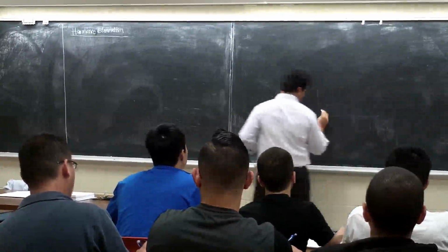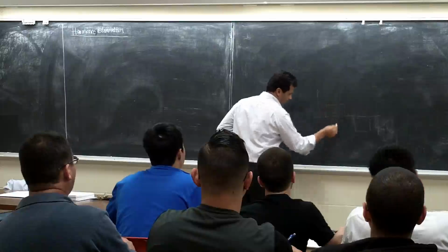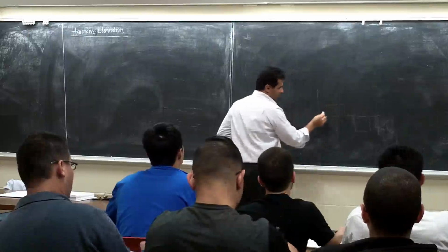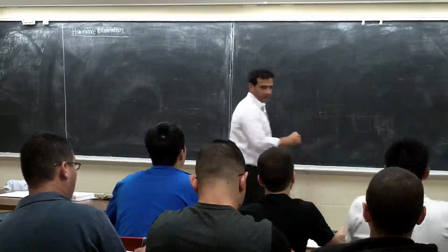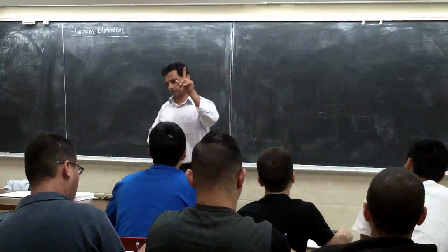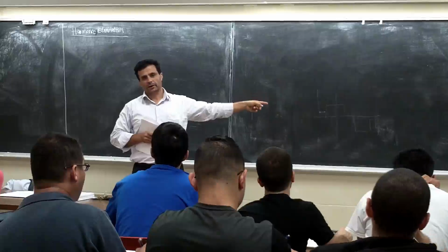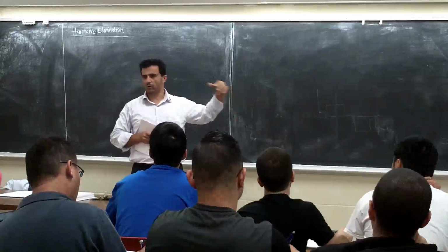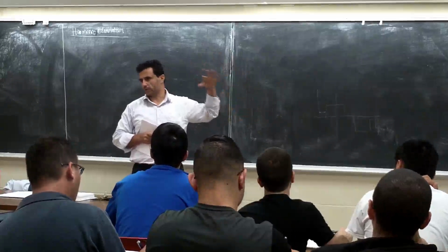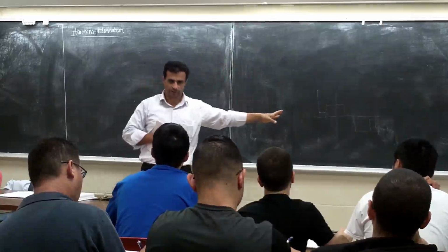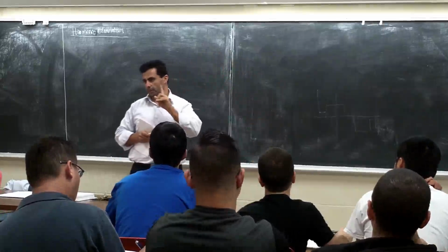So they call this one notch. Basically, look at a quarter cycle, right? We have only one notch here, right? You can control one element. You can, for example, say I can eliminate the third harmonic, or I can eliminate the fifth harmonic, or seventh harmonic, whatever. That's it. I can do one.